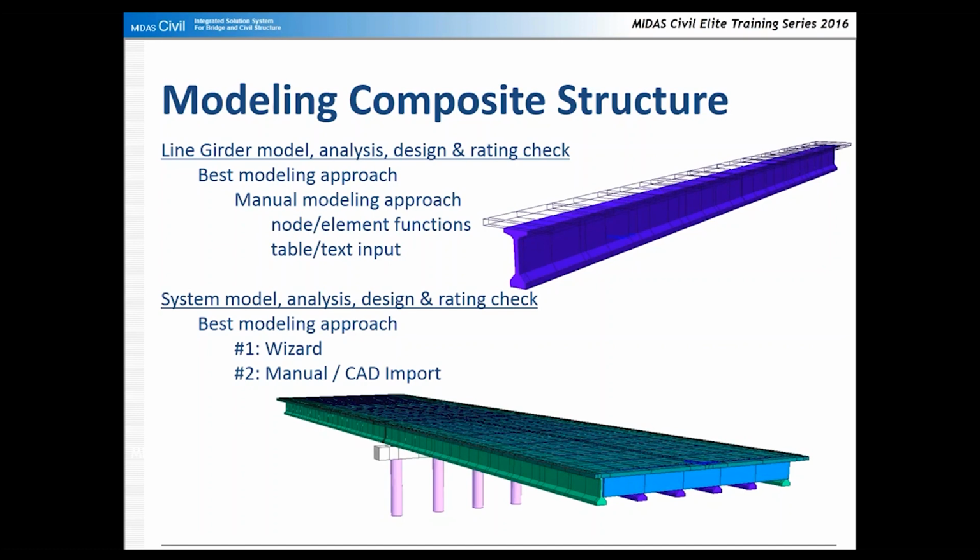And even though it's very simple, it's still an FEA program, finite element analysis software, so you're able to get accurate analysis results. That's the main benefit: how easy and fast it is. The downside is that you're not working with the entire system, so it can be more conservative or a little less accurate.